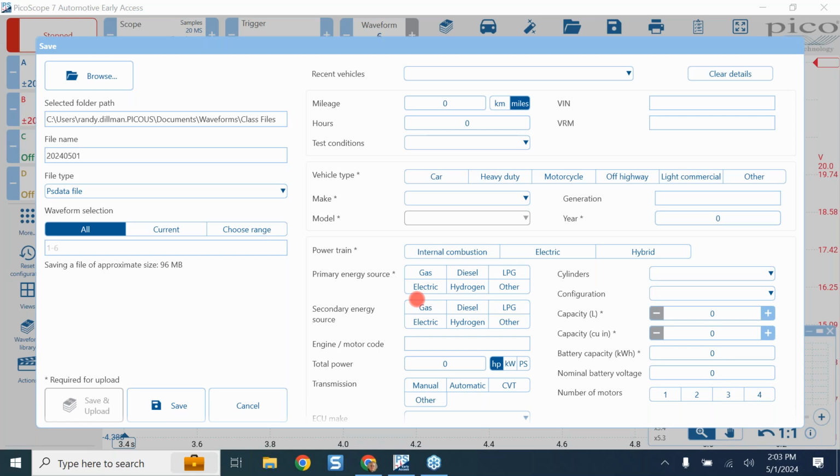So watch everything, because remember, an 8-channel 4823 is a common ground scope. Keep an eye on everything, because you don't want differential voltage going over 20 or 30 volts. You're going to create a problem with 4823s. Most of my power users are well aware of common ground versus a floating ground scope, because if they bought it, they might have received some instruction from me or a phone call from me along the way, just to verify.